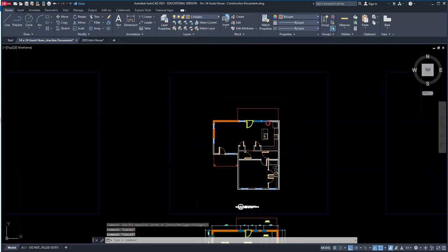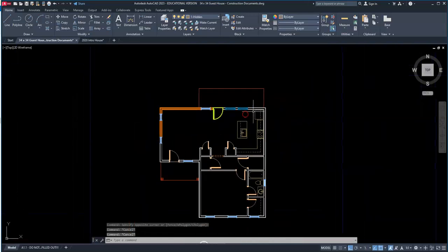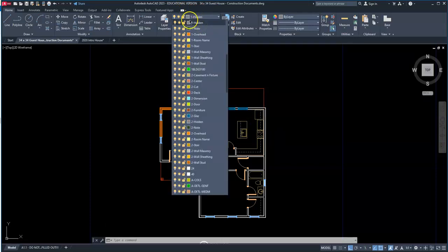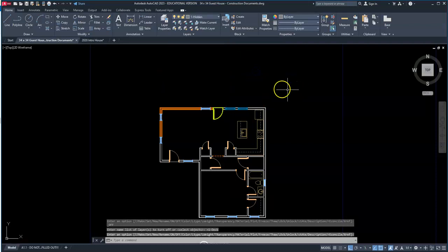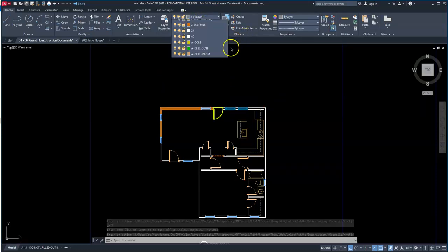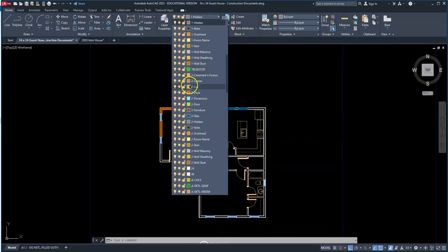All right, so the beauty of AutoCAD is that when we change these layers, we can turn things on and off quickly, which is why we group things together within certain layers, as well as the line thicknesses, as we mentioned before. So good thing to know if we ever wanted to show a drawing without the porches. For example, we can turn off the light bulb and those porches will disappear. A lot of utility there with the layers and turning layers on and off.